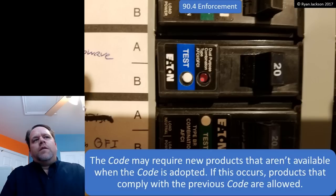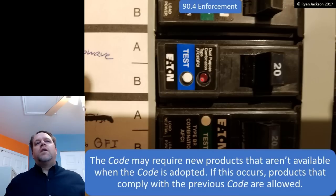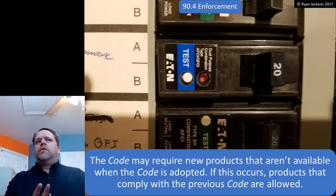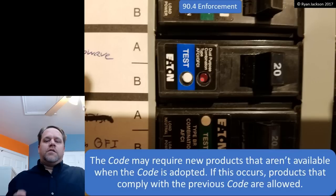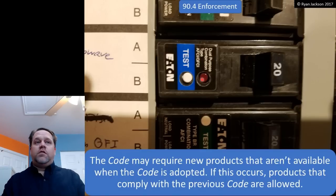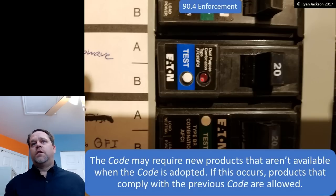The last sentence in 90.4 is an interesting one. It says the code might require new products that are not available when the code is adopted. And if that happens, products that comply with the previous version of the code are allowed. What we're looking at here in the photograph is an AFCI circuit breaker. They first came into the code back in 1999, and we used to use what's called the branch feeder type of AFCI. And then in 2008, they made a change saying we need them to be the combination type AFCIs. For a short time, it looked like none of the manufacturers were actually going to have a combination type available in 2008. So now what are we supposed to do? We can't wire houses because the AFCI doesn't exist? Well, no. What the code says is, if that ever happens, just go back to the previous version of the code and you're good.